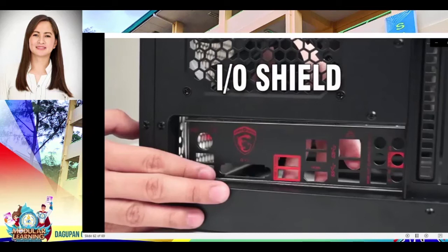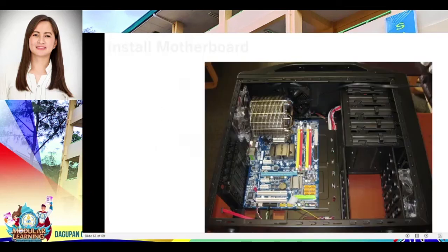Internal build. Internal build is also the input-output shield. This should be the front or back panel connection for features such as the power switch, audio jack, and USB ports. If they are not labeled, consult the manufacturer's documentation and label them yourself now, before other parts are installed in the case.